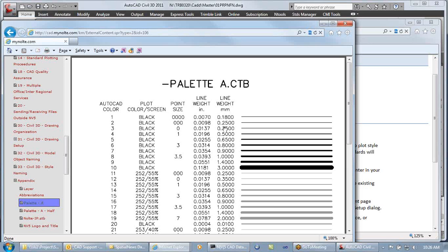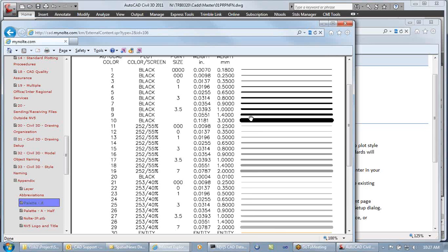My annotation text we typically do is green, so you see most of our drawings' text is green. Larger text like titles and labels will probably go cyan. It's a little bit fatter. The object line of your drawing, you're going to start using the blue, magenta, and white. And then if you need some really huge fat lines, then you start getting up into these gray colors here that AutoCAD has. So that's your bold black line work.